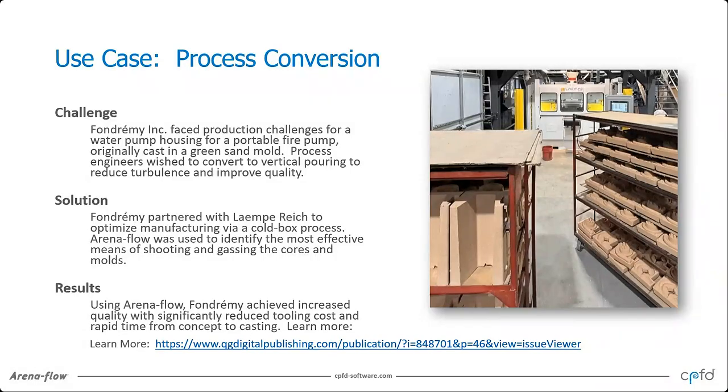It was originally cast in green sand, and the process engineers wanted to convert to vertical pouring to reduce turbulence and improve quality. And so our partner, Lempe Reich, partnered with the foundry to optimize this. ArenaFlow was used as part of that tooling design, and they switched to the cold box process to identify the most effective means of shooting and gassing the cores and molds. And using ArenaFlow, the foundry achieved increased quality with significantly reduced cooling cost and rapid time from concept